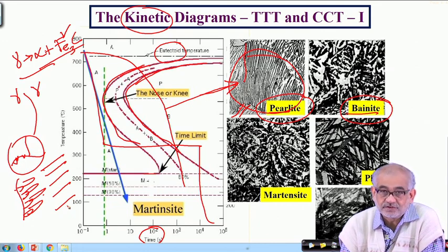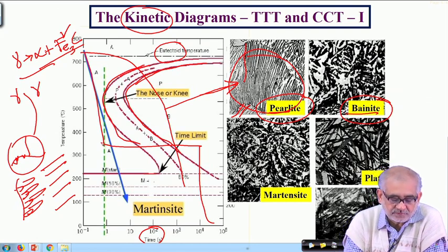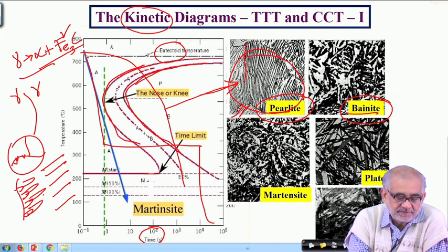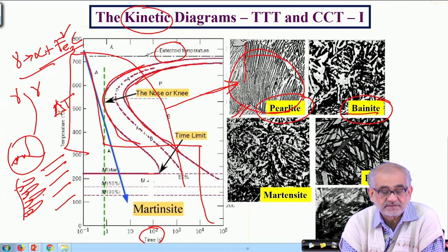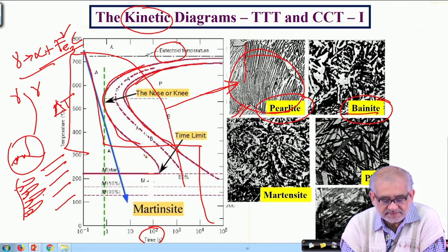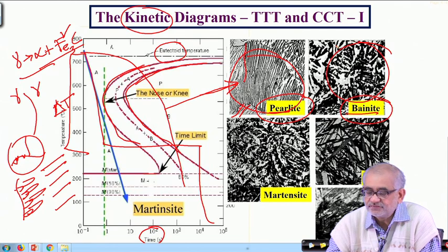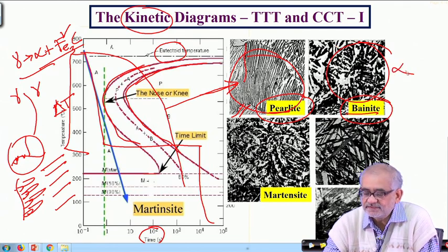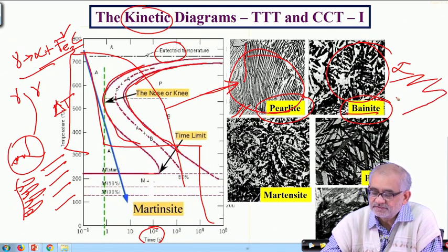On the other hand, when we talk of bainite, which essentially forms at a much lower temperature, and because of lower temperature, now we are talking about a much larger undercooling and hence much greater driving force. So under this larger driving force, when the transformation begins and ends at a lower temperature, we end up getting a microstructure where, for a difference, the ferritic sheaves nucleate first. So essentially you'll see such sheaf-like structure just like a leaf.